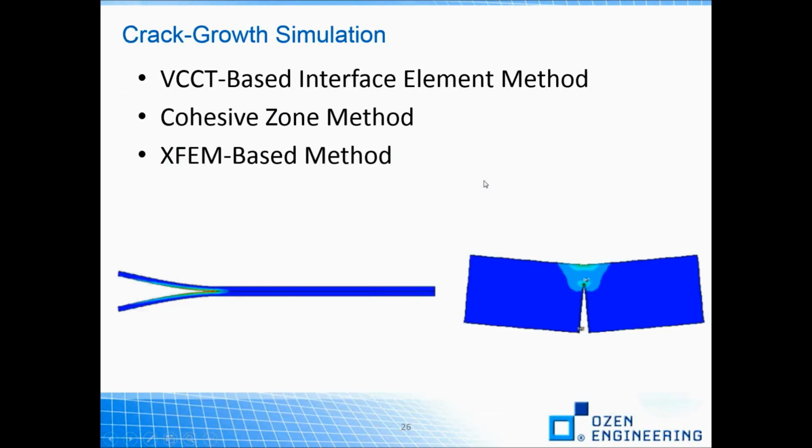So ANSYS provides alternative methods to simulate the crack growth as well in homogeneous and composite structures. Cracks may propagate when certain loading conditions are reached or certain localized conditions are met, or can propagate along the interface between the layers of a composite structure, i.e. the interfacial delamination. And depending on the case, one can simulate crack growth along a predefined path or along an arbitrary path.